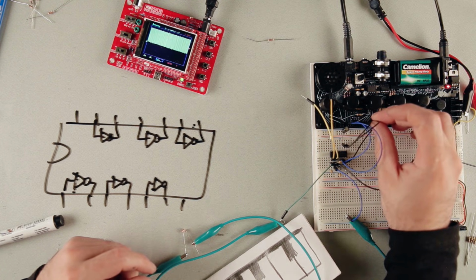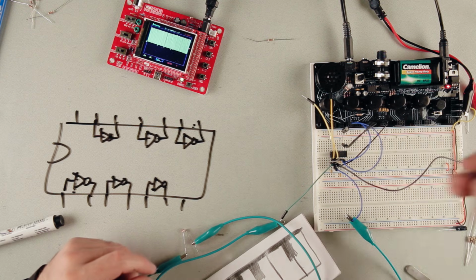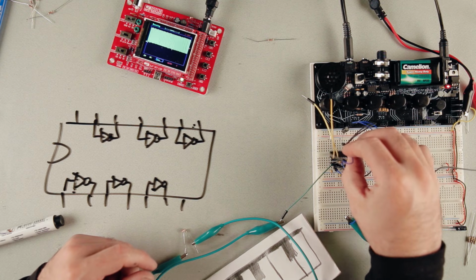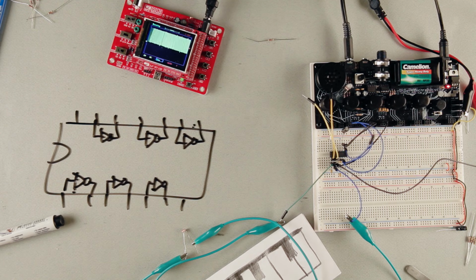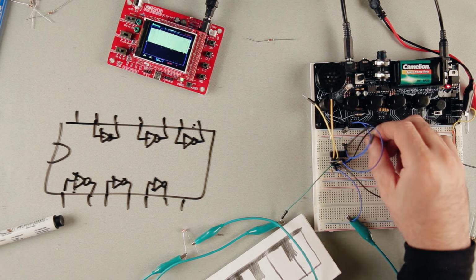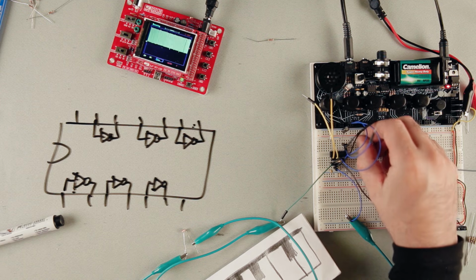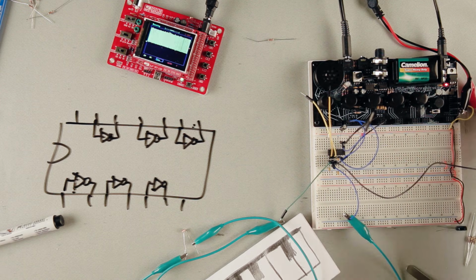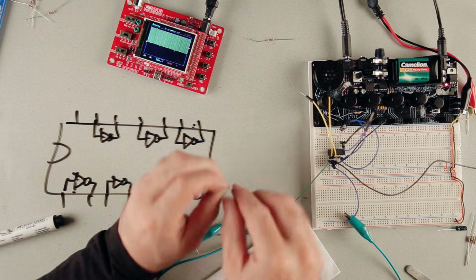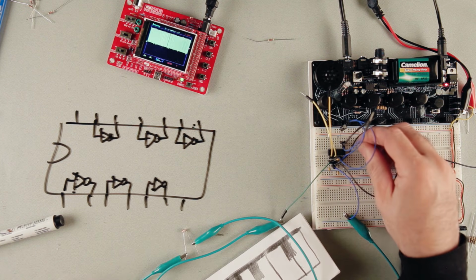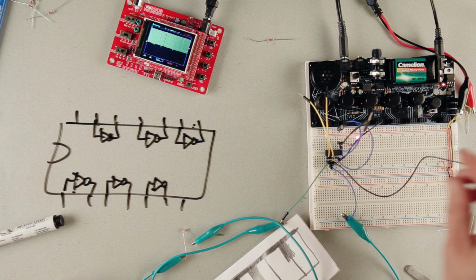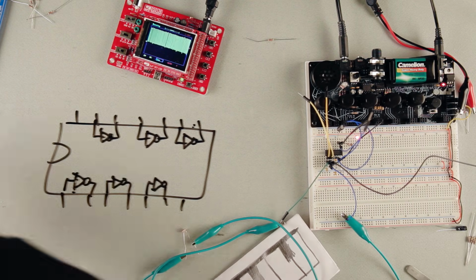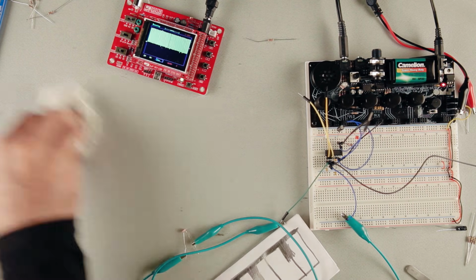And now I'm also going to introduce LEDs. So what I'm going to do is take the output of this, and I'm going to take an LED. I'm going to connect that here, and then through a 1K resistor, I'm going to be able to look at the signal. So there it is blinking, you can see. And the schematic for that.